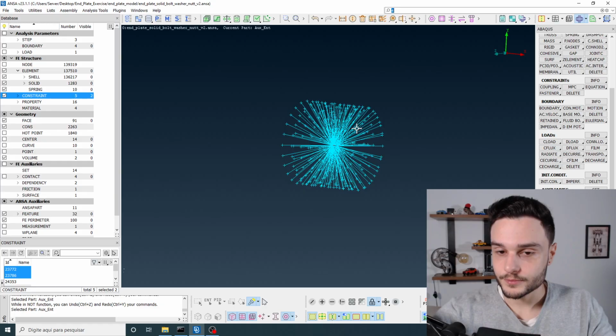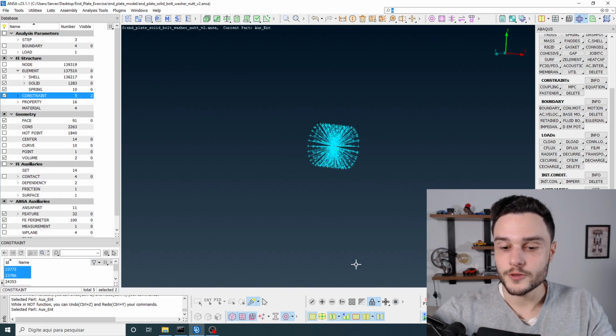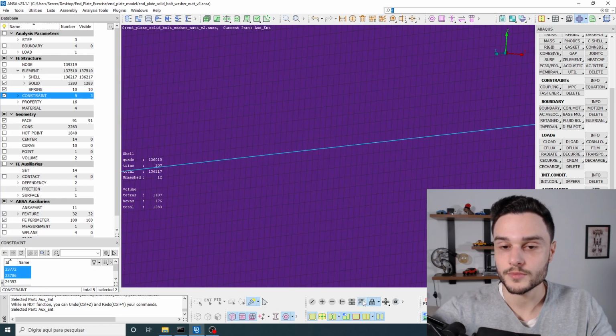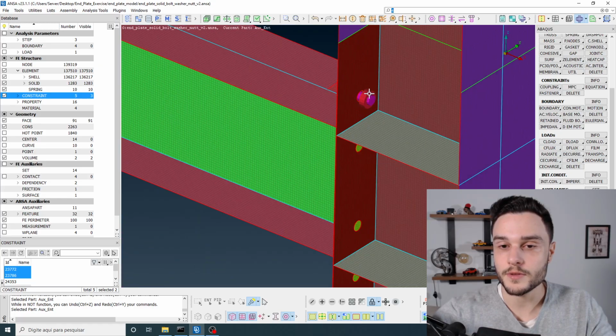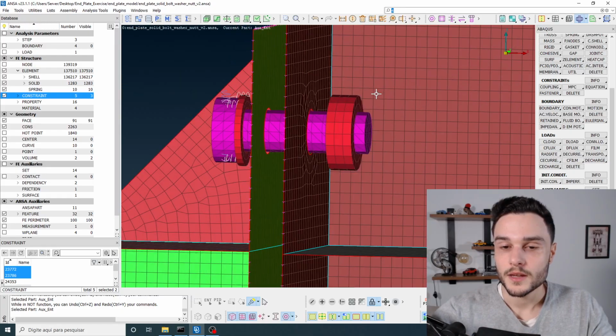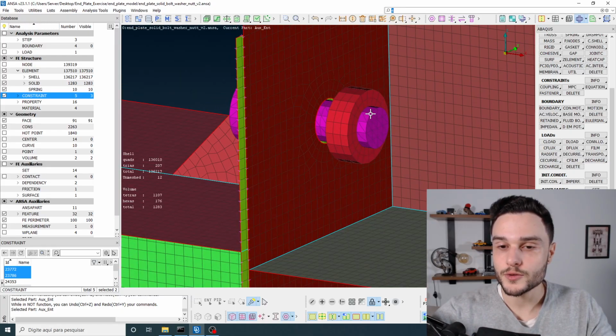Okay, so I'm going to unlock and lock again so that I have these two couplings visible. And then I'm going to use these two couplings as the lock view, and then I'm going to use the invert tool. So it's going to show everything that was not visible, and it's going to hide everything that was visible. And then I want to create 2 points that pass through the axis of this bolt.